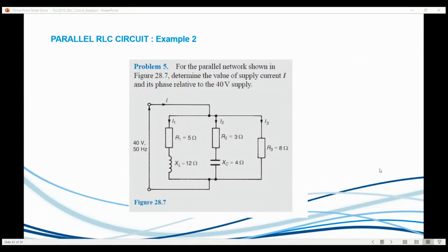Do we add the two capacitors? Yeah, the thing is, you can first find the reactances, and then just add them up. You add the reactances, not the capacitors, because capacitors in series are like parallel resistors. Add capacitive reactance.